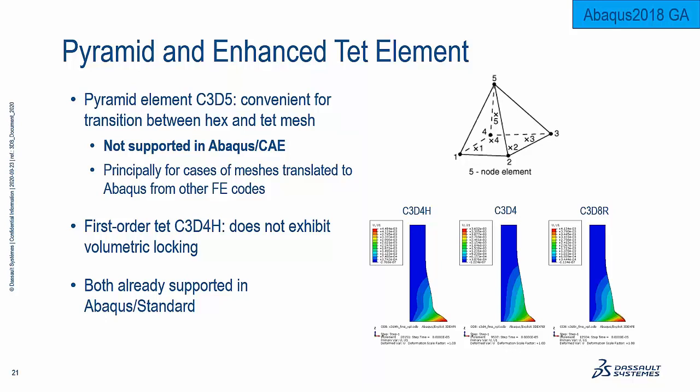And so therefore they are problematic for scenarios where there is locking of the elements, of massive deformation and pileup of elements, as you're seeing, for example, here, the difference between the C3D4 for our copper rod or Taylor impact versus the C3D8R, which is a standard element which always compares very well as long as your mesh is adequate to tests.